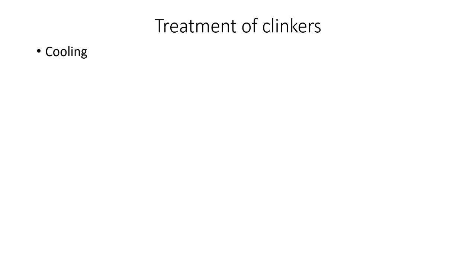The next step is addition of retarders. What to retard? Okay, so we'll see here, as the clinker passes to the grinding mill, it is mixed with the proper amount of retarders like gypsum. Means what does this gypsum retard? Okay, the retarders are negative catalysts that control or slow down the time of setting of cement. It also avoids the undue rapid setting or stiffening of concrete.